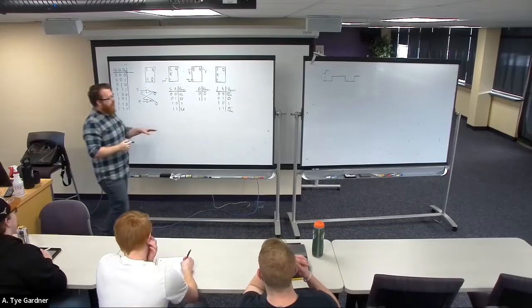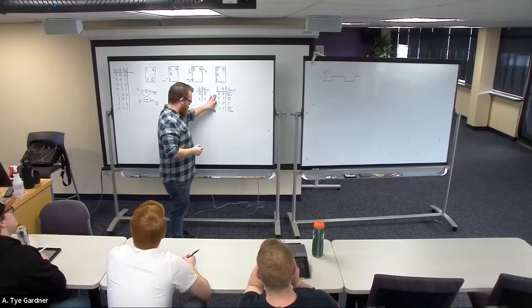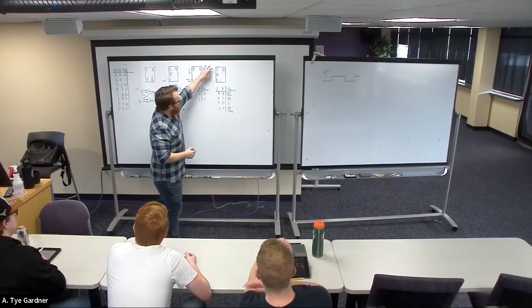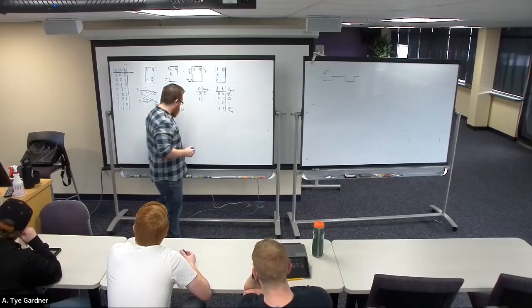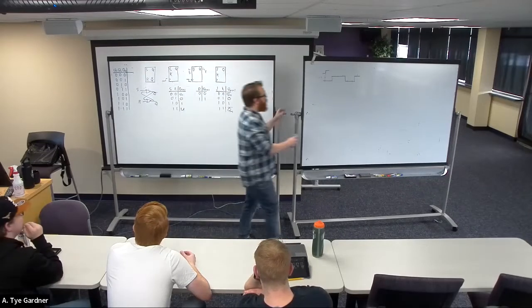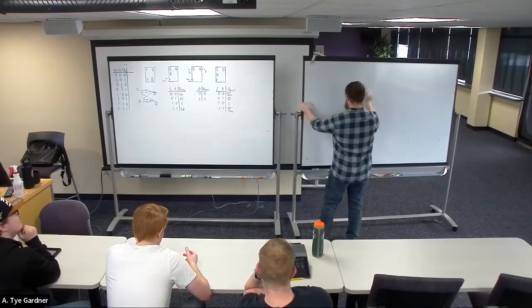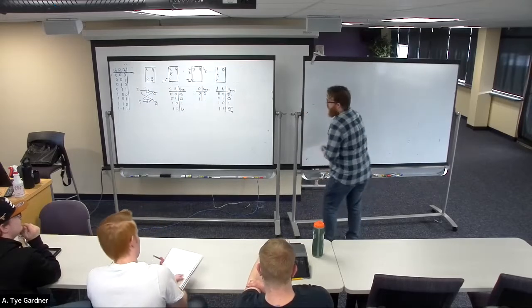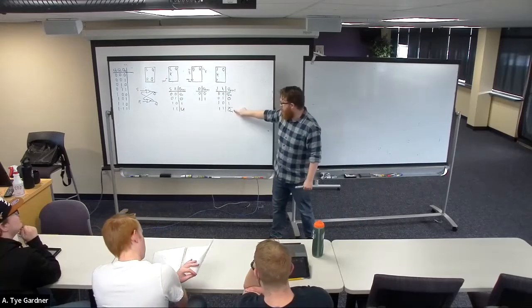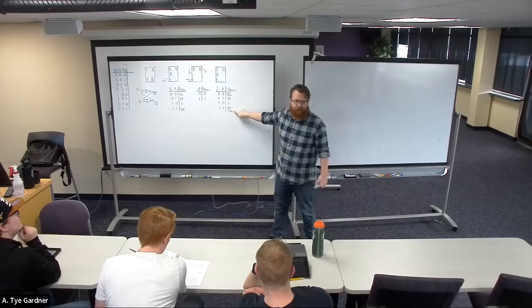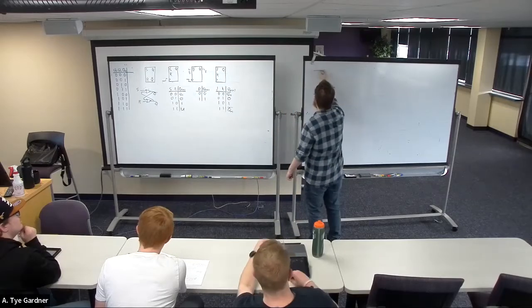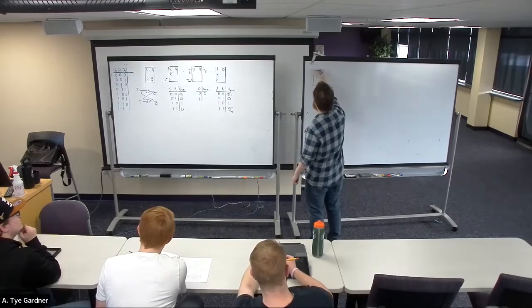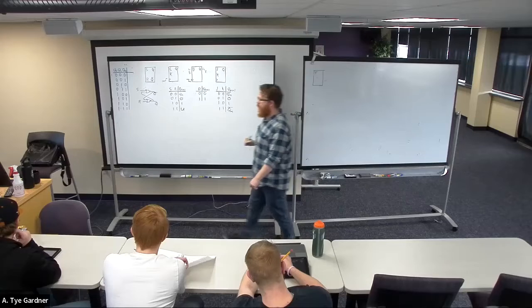And what's nice then is if I stick 2 of these together, the J and K input, if I attach them together, I get a new kind of flip-flop. Because if they're attached, I can only remember or flip. That builds us the T flip-flop.